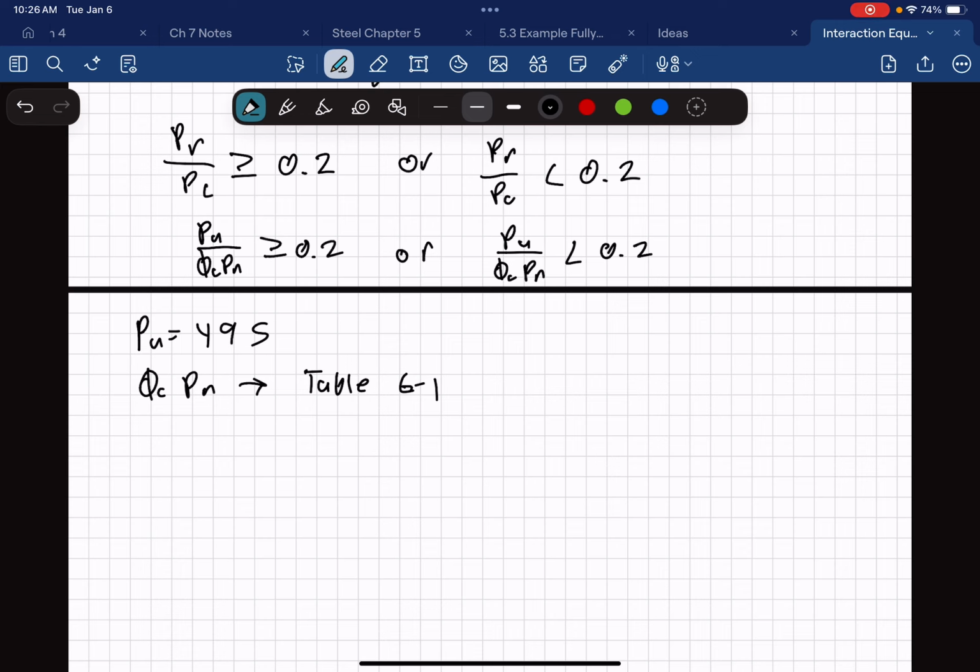It has a value for 24 and for 26 feet. Those values are 1140 and 1060. We can just average them because it's right in the middle. We would have to actually interpolate if it was not directly in the middle, but it is. And we're going to get 1100 kips of axial strength. W14x132s are pretty strong columns. So let's double check again, 1140, 1060. Yep, that's exactly what it will give us.